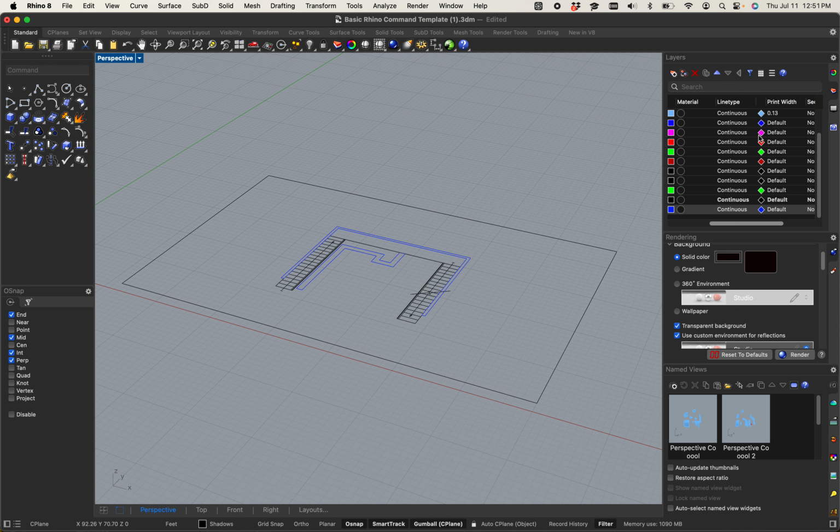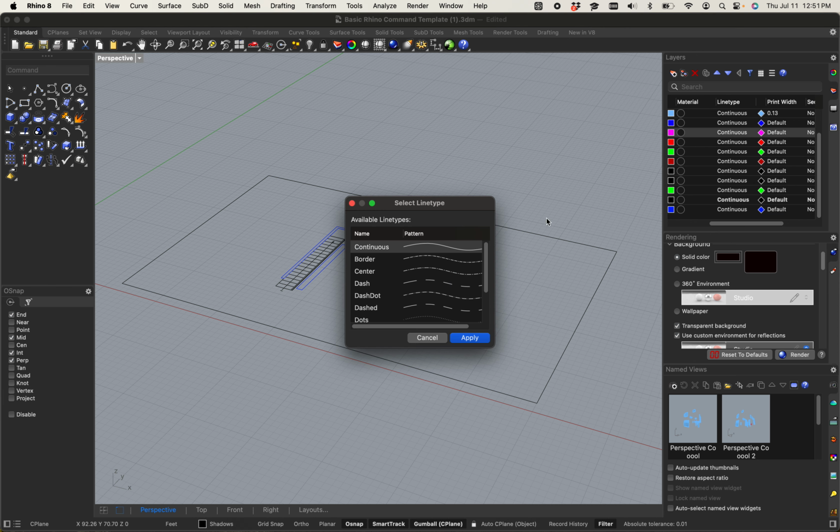If you go to any of these layers, you can choose the line type. Instead of continuous, you can change it to dash, dot, whatever. However, the only thing there, Katia, is if you change the scale of the drawing, it doesn't change the scale of the line, so you have to mess with it all the time. And unfortunately, when you take it into Illustrator, it goes into all these little separate pieces, so I can't even change it. That's why I recommend that you do all line weight and all color and any of the actual graphic stuff in Illustrator, just because it handles it a little bit better.